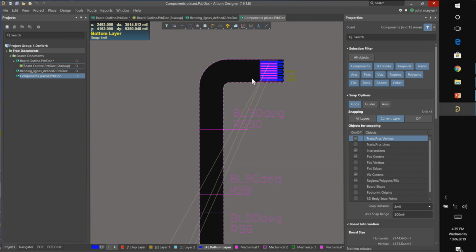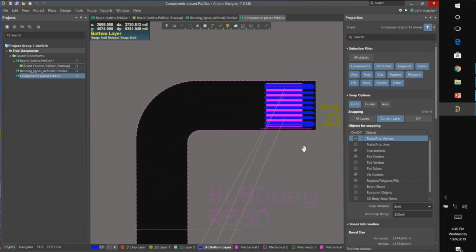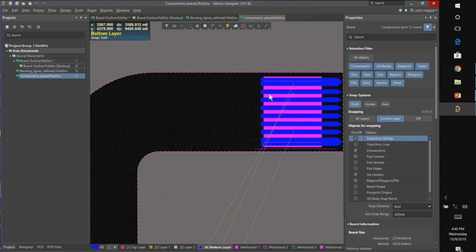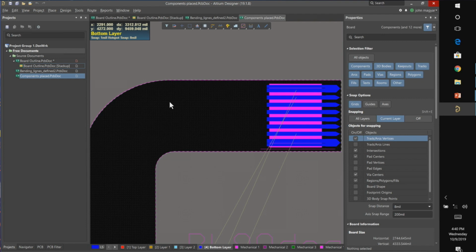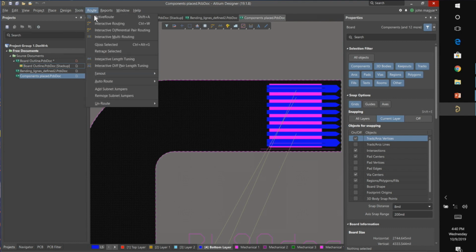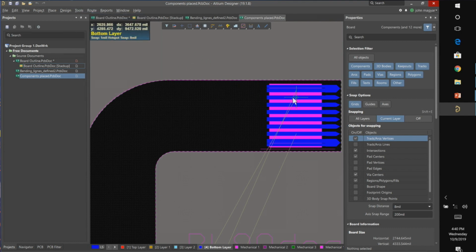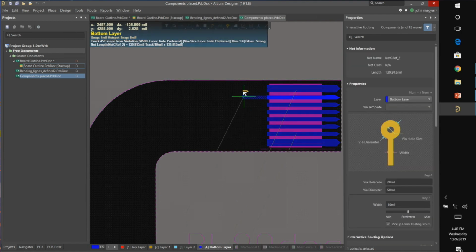Not sure if you saw any of the advanced routing that Derek did earlier. One of the things you'll be able to do here, and I know this has traditionally been a problem, is okay, I got my flexible shape, now I want to start routing this. If you go into the interactive route mode and start routing a pad, it's probably complaining about some design rule of width or something, but I can use different arc modes.